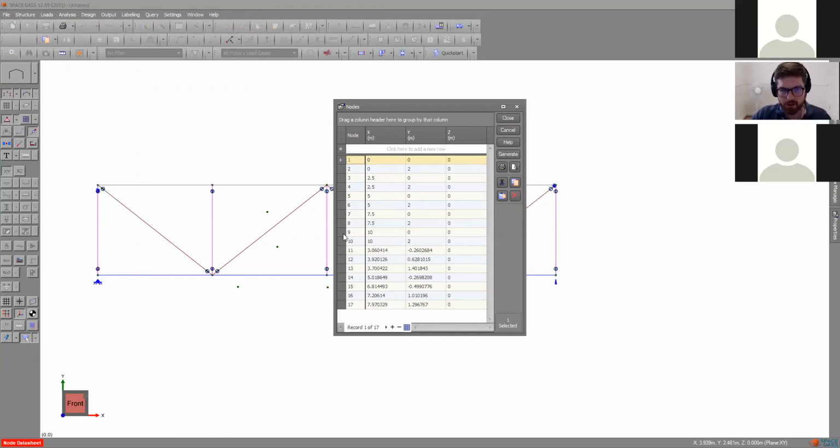And you can see the nodes are stored in a pretty normal format, node 1 to 10, X, Y, and Z geometry. The wizard generated pretty sensible nodes. They're located at 2 meter widths or 2.5 meter heights or vice versa. But the nodes I've clicked, they're not assigned to any sort of grid system. They're just nonsense. So in terms of developing a precise model, I definitely recommend the data sheet.